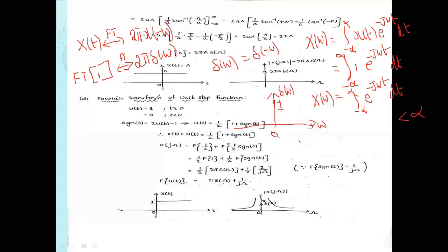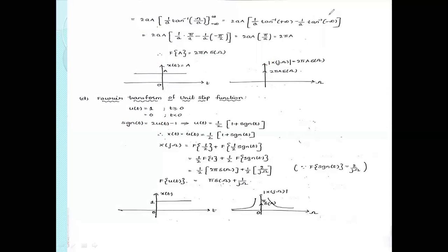So the Fourier transformation of x of t is x of omega. But here there is a 1, and its Fourier transformation is 2 pi into x of minus omega. So both are the same. So it becomes 2 pi into the delta of omega function. That we can get from the duality property also. Remember that the Fourier transformation of a constant is 2 pi into delta of omega.